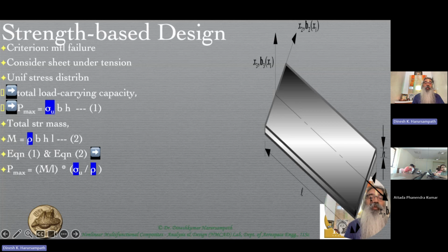And this is also a particular percentage of the gross takeoff weight coming to us from the design. So we can't go beyond a particular value of that. So this is not too much of a design choice for us. Or even if it is in the case of M, it's not a material choice. The material choice is what is highlighted in blue over here, which is your sigma U divided by rho.